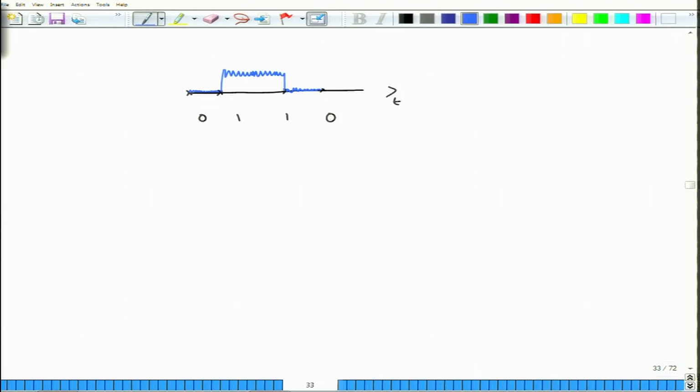This is actually the case where the system is very good, because what you can do is put up a threshold here, call this threshold I_TH, with a capital I. This threshold is constant, although the line that I have drawn does not really show a constant. What you now do is sample this signal at the midpoints of the symbols. This midpoint was actually 2 slots, so this is 1 slot and this is 1 slot. You sample these signals here.